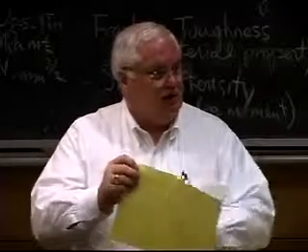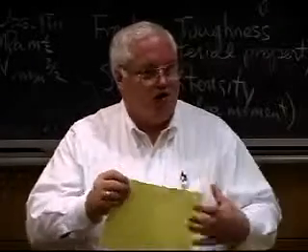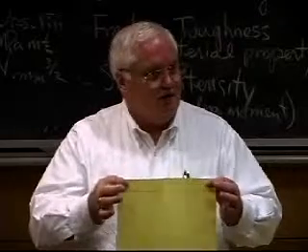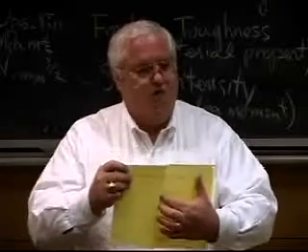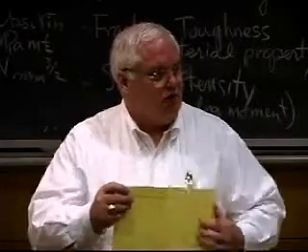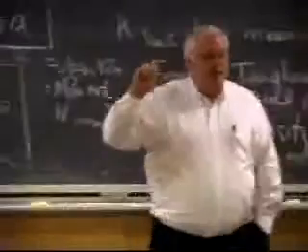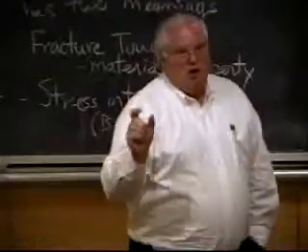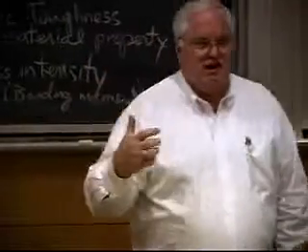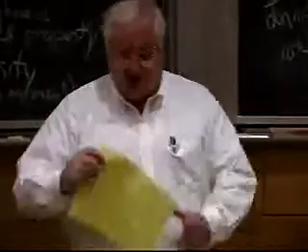It's just a stress in tension times a lever arm. Only it turns out, the mathematics works out, that it's the square root of the lever arm. Okay? Now, there are whole books that solve what this stress intensity should be at the tip of the crack.